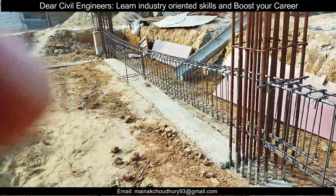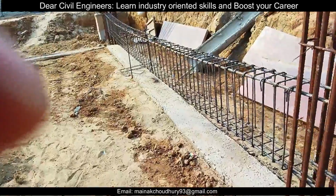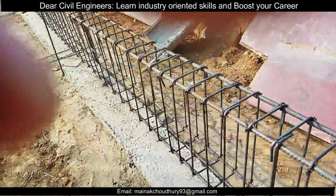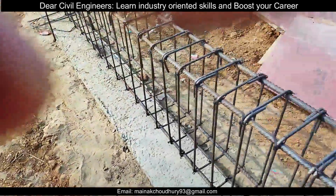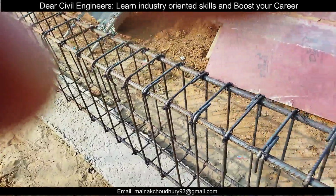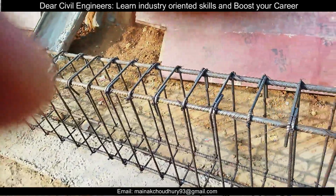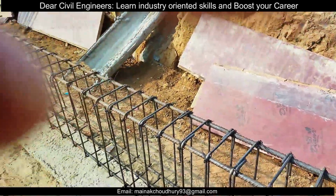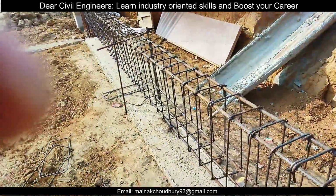I hope that next time when you go for an inspection, it will really help you. And in the bottom, as you can see here, since this is the tie beam, after compacting the soil, PCC was done. So the bottom will be supported by the PCC, and on the sides we'll give side boards using plywood, and then the casting will be done. I'll surely make a video on the casting day also.